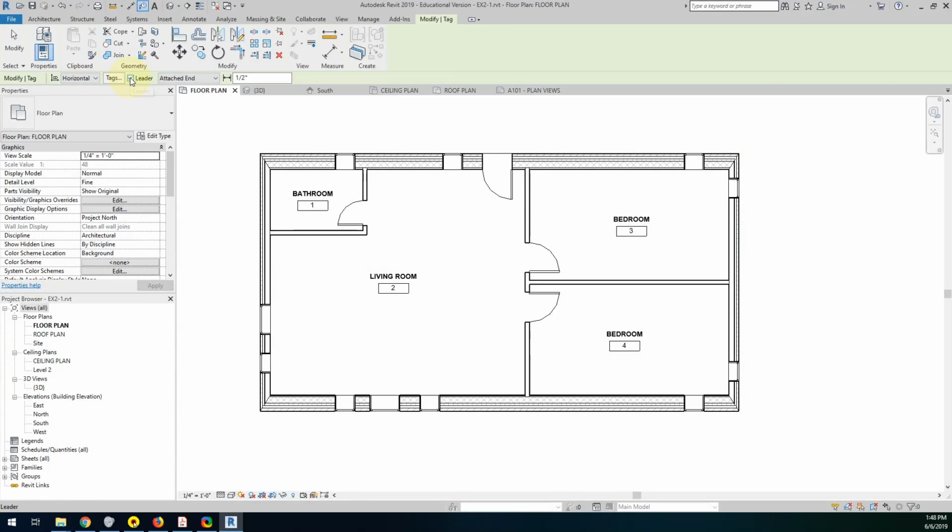So I'm going to tell it to not put a leader. So if I hover over a door, place it, and click on each door. And each door should have a different number. Now you'll note maybe in your case you might be missing a number. Don't worry about it this time. We'll talk more about that in project 2 and how the door numbers should be.